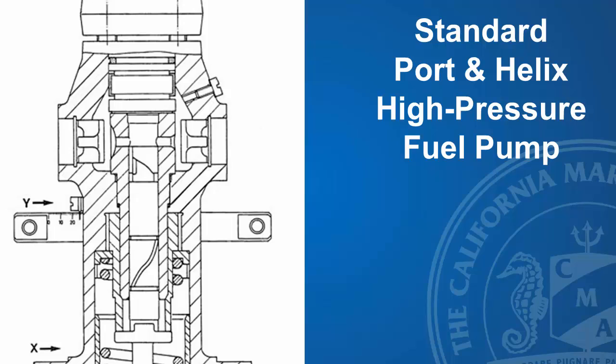There are no sealing rings on this. Specifically, leakage is controlled by the tight fit between the pump plunger and the pump barrel. These cannot be replaced separately. The clearances are so tight that they have to be installed and removed as a unit. So when you're talking about distillate fuels, you're looking at about 7 to 9 microns. A micron is a millionth of a meter. So you're talking very, very tight tolerances.